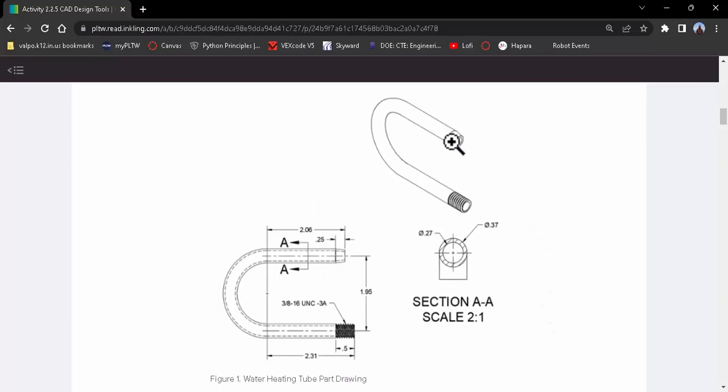We just need to add our taper here, shell it, and then finish it off with a threading on the bottom. So for our taper, let's take a look. We're going to notice that the length of the taper is 0.25. It doesn't really identify much after that. But just for this case, we're going to give it a 10-degree taper edge all the way down that entire length.